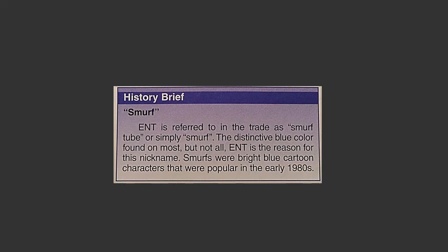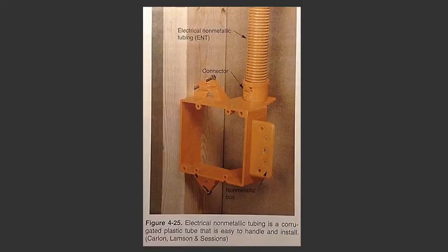There are some restrictions and limitations to the use of ENT. It cannot be used for hazardous material, cannot be left exposed with some exceptions, should not be used as supportive means, cannot be used for direct burial applications, and cannot be used for voltages exceeding 600 volts.